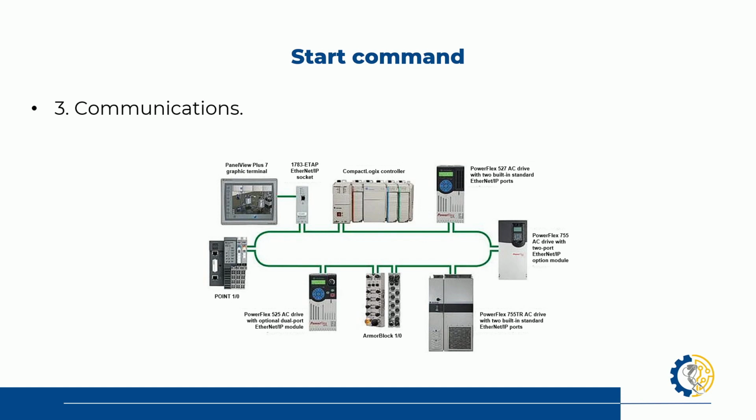And all other devices need to be added at the same time. Now here, it's connected by various racks at the same time. So what this topology does, and I explained this a little bit in our network course, is if this side fails with communication, the devices don't need to stop and they continue running, so that there's no stop on the line. Okay, so this is a network issue.